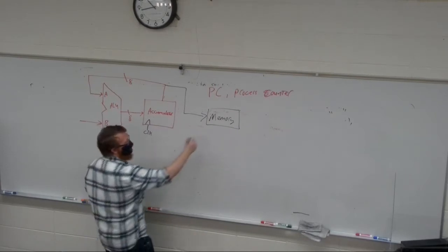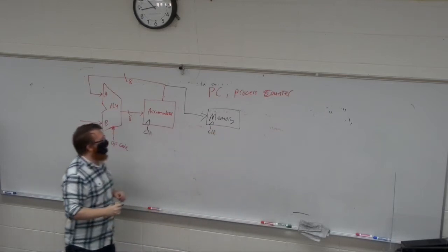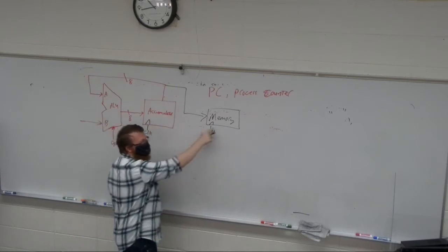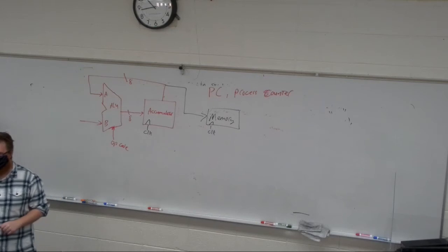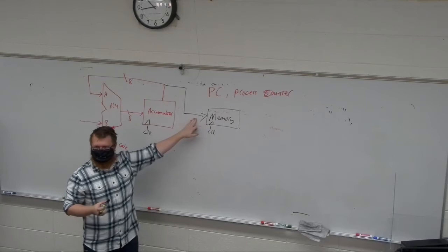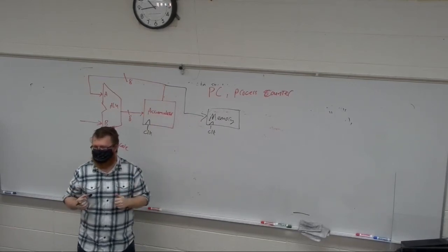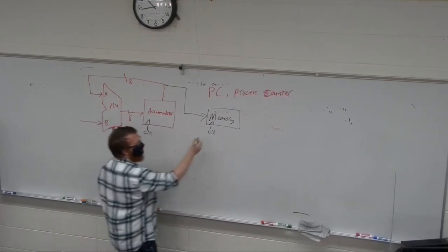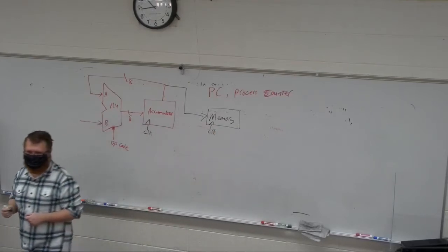Right? So if I have the clock here, and I update the output of my accumulator at the same time I try and record it in memory, we have a term called a race condition, which is a race between storing what's on this signal and updating the signal. And we have no way to know which happens first. So instead of having this, a fine way to do this is to call that not clock.